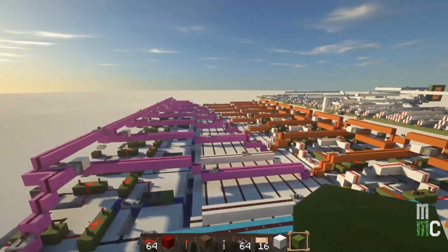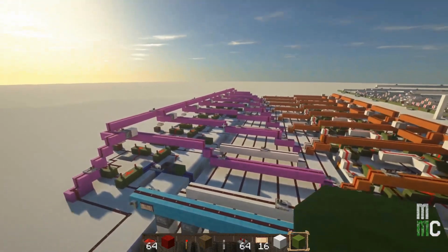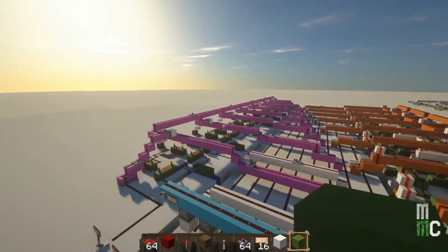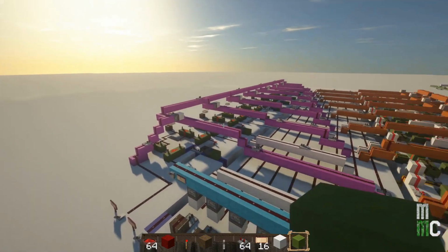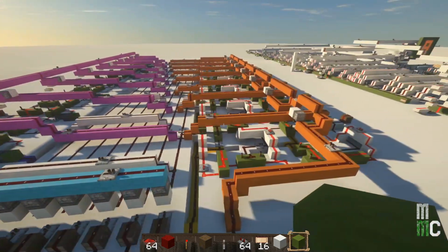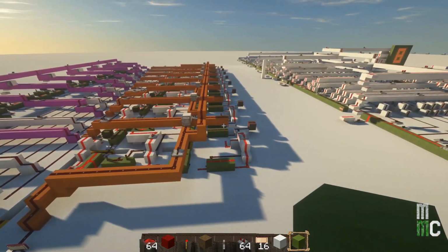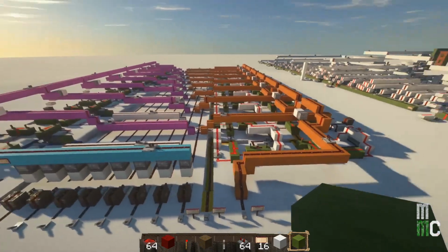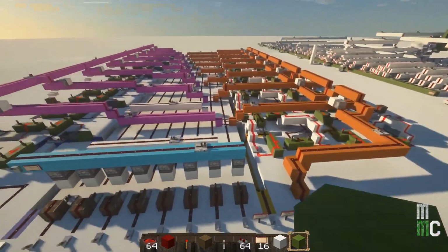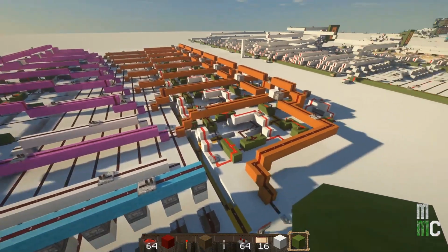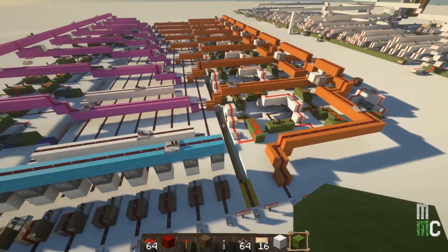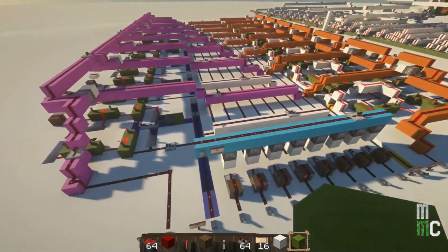So we want to be able to put our value on here and then swing it to the bus. Okay, so I have got everything done. We have built our magenta lines for the control lines and the output from register A back to the bus. We have the orange ones for register A back to the bus. Over here is register B. So the registers now input from the bus and they output to the bus, and they have a switch that we can use to turn that data on or off on the read.